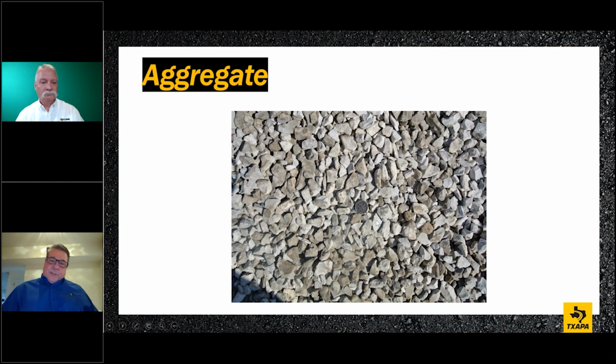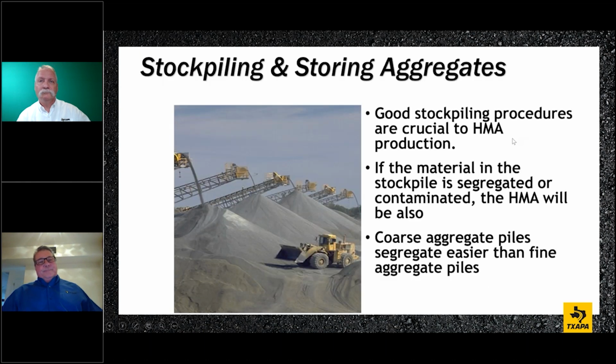But you can see here, there's a dime, and you can see how clean and angular this aggregate is. You can see there's no clay balls. There's nothing involved in it. It's very clean, very durable looking, very uniform looking. That's what we want to see. Either 80 or 95% crushed faces or 100% crushed faces. Again, that's going to give us that angular ability for that rock to interlock together when they're putting the designs together.